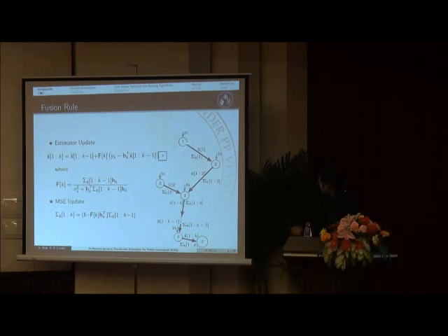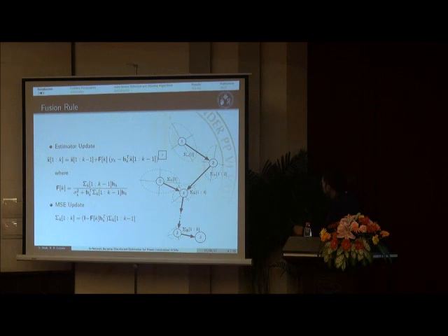Here, basically, the leaf node, I mean the sensor node, measures its own measurement y1 and forms the estimate x1 hat and its variance sigma, and forwards it to the parent sensor 2. Sensor 2 measures its own measurement y2 and fuses it with the measurement it receives from y1, and forwards it in the form of a single flow or packet to its parent. In this way, the measurement goes to the sink node. We can see in this ellipsoid form that the error covariance matrix, in the form of a covariance ellipsoid, is reducing as we add more information. This is the main motive of this paper.